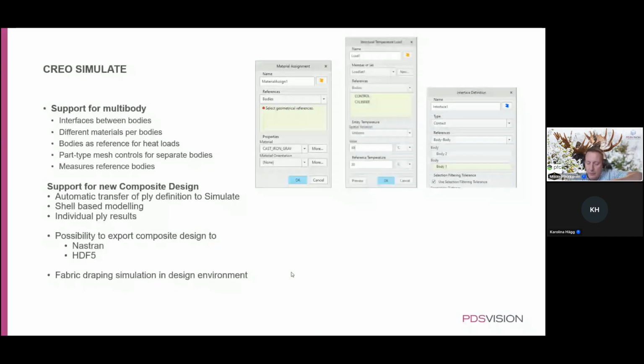And just applying those plies can be a bit tricky since you have to know where one ply ends, what the orientation of the ply is, what the thickness of the ply is, and so forth. But now the system can read all that information about the internal ply structures directly from the design model, which of course makes it less error prone and much faster to start using.